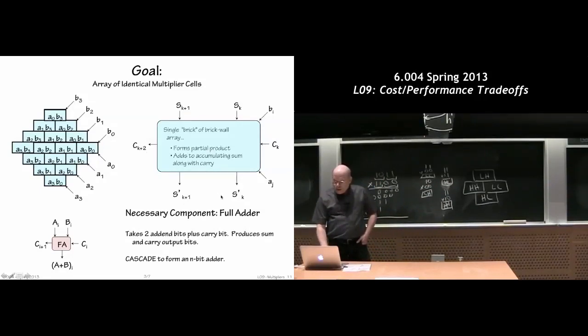So in general, what I'm going to do is multiply A times B to come up with a 2-bit result. I'm going to add it to those bits of the partial product coming down from the top, and with a carry in from any carry outs of previous operations in bits with less arithmetic significance, and I'm going to produce a 2-bit sum and a carry out.